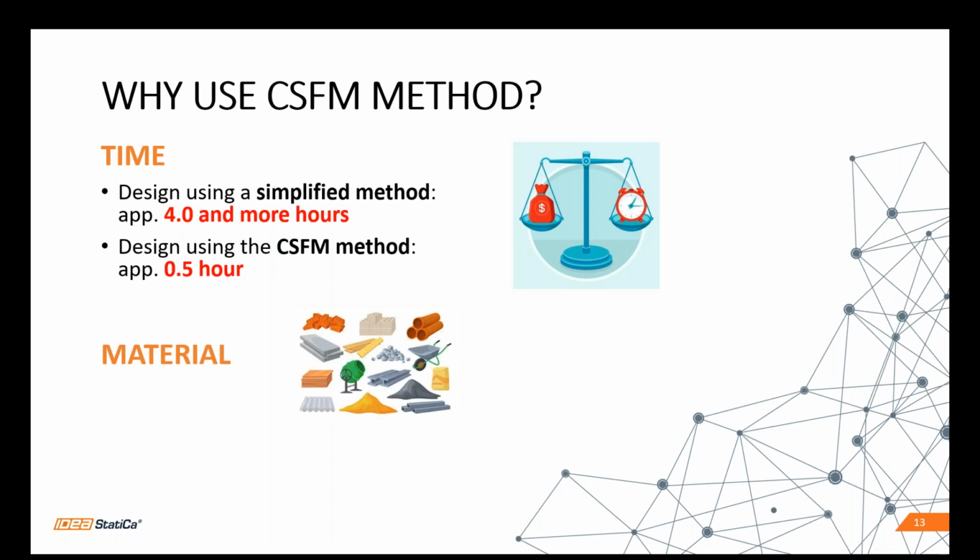So thanks to this method, you may know where you need to add more reinforcement, or where you can afford to cut back the bars. And the last but not least important reason is that you will get all of the important code checks, including SLS checks, as for example, crack width checks or deflection check.